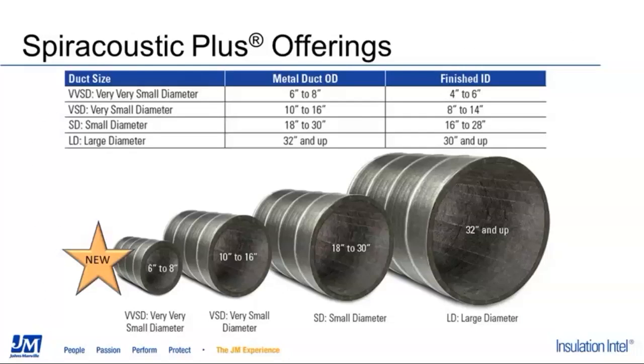So next we'll talk about Spiral Acoustic Plus offerings. Spiral Acoustic Plus is uniquely engineered to fit specific duct sizes ranging from our new VVSD, or very, very small diameter, of 6 to 8 inches to LD, or large diameter, of 32 inches and up. For each of these sizes, the kerfs in the Spiral Acoustic are cut at different measurements to ensure a snug fit against the interior wall of the duct.